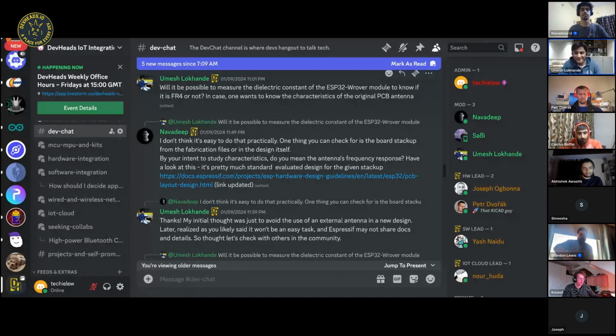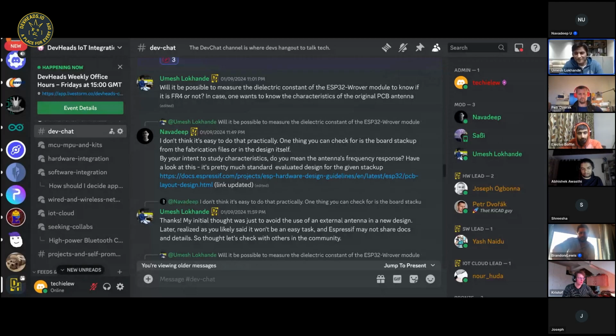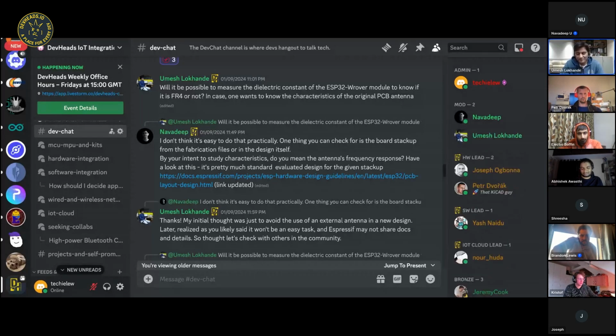As you know about me, I have companies, and I'm always looking for how I can cut the cost of components. So if I do not get the module, I would probably get the component memory and the core ESP32 and put it onto the PCB. Of course it looks crazy, because I did it before and I'm using a module right now in the product, along with STM32. So for Wi-Fi I'm using ESP32 in the product, but the real computing is done by STM32.